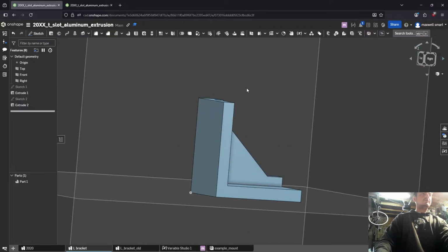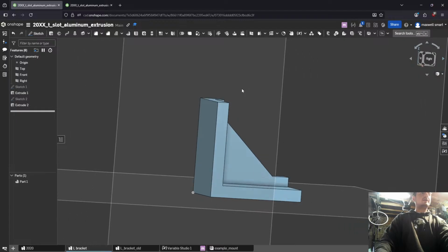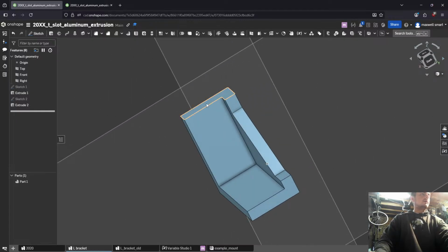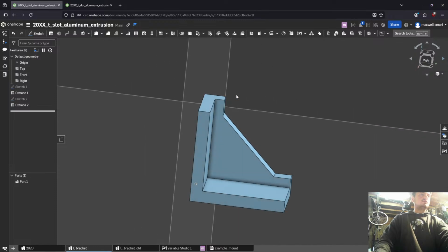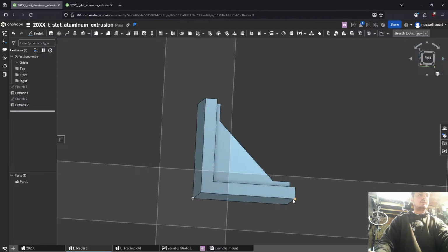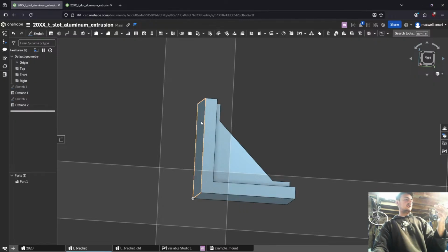What I can do is I'll create a midplane, and then I'll draw the side profile in the midplane and do a symmetric extrude. And then on that midplane I can draw all 4 of them. I don't really know how I'm going to do that. That's kind of an interesting geometry, especially because it's all covered in paint.